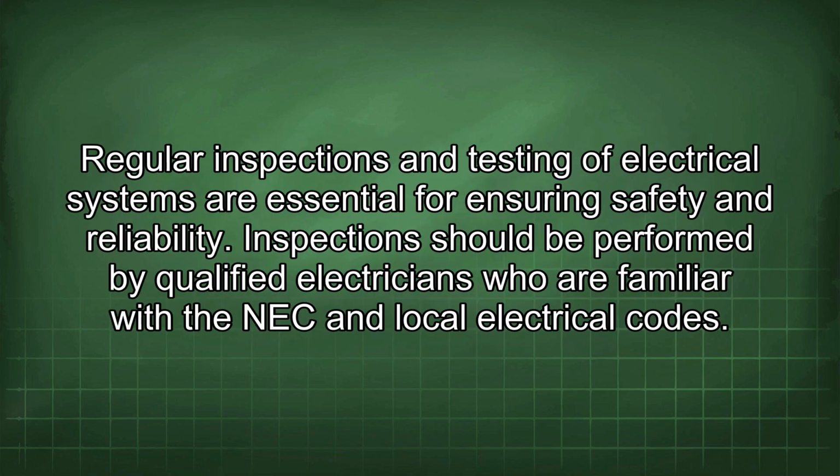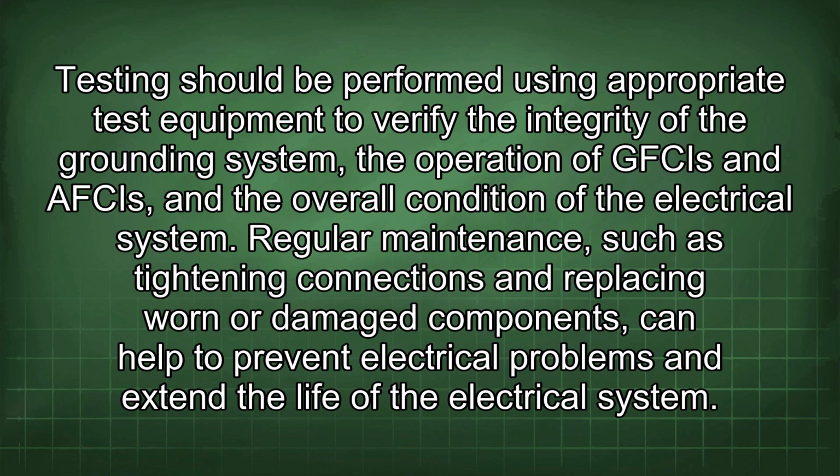Regular inspections and testing of electrical systems are essential for ensuring safety and reliability. Inspections should be performed by qualified electricians who are familiar with the NEC and local electrical codes. Testing should be performed using appropriate test equipment to verify the integrity of the grounding system, the operation of GFCIs and AFCIs, and the overall condition of the electrical system. Regular maintenance, such as tightening connections and replacing worn or damaged components, can help to prevent electrical problems and extend the life of the electrical system.